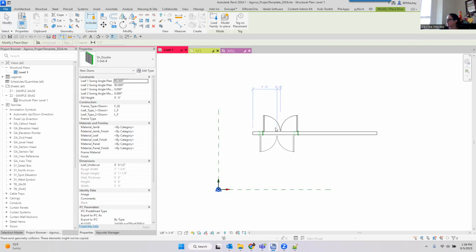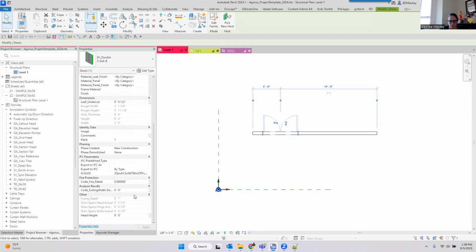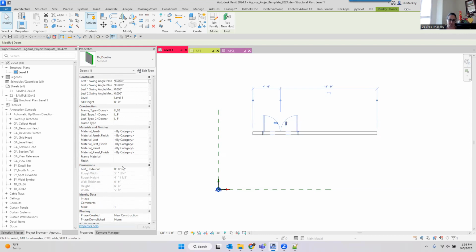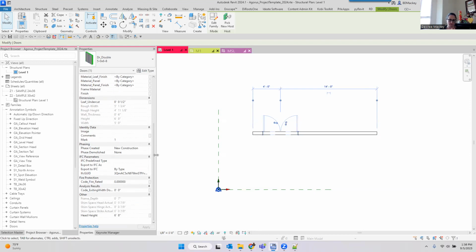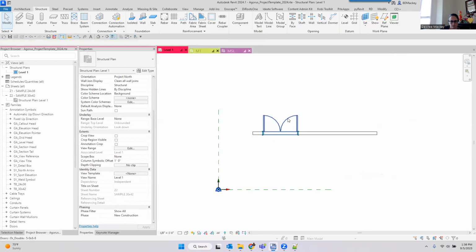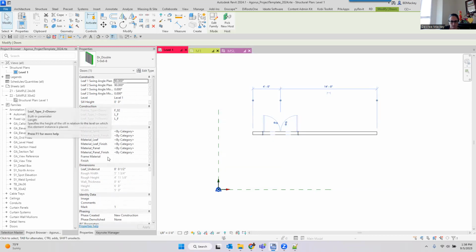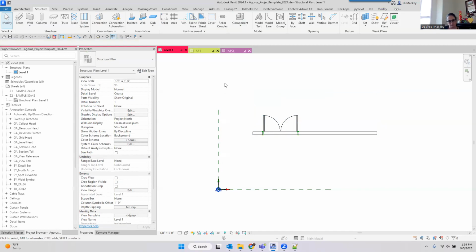And so now that I've loaded this door into here and I select it, I made that an instance parameter. I grouped it under, what did I group it under? Forces. Did I group it under forces? Am I not saying it? Did I hit cancel, like an idiot? I must have hit cancel. But what I was going to show you if I did it properly is now every single door in the project would have that value for you to grab. You could also go use that shared parameter to tag it if you want, or you could use it for scheduling. So that's truly when shared parameters are there.